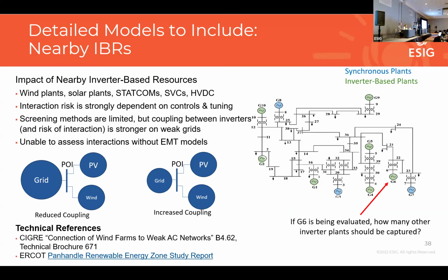So the big one is, of course, IBR models. And you're always going to have some region where you're interested in the dynamics. And so there's some IBR plants that are going to be a given that you're going to have to model with a detailed IBR model, right? They're the reason you're doing the study, right? And now in the region, as we look out further, zoom out a little bit from that very focal point, there's potentially going to be other IBRs in that system, right?